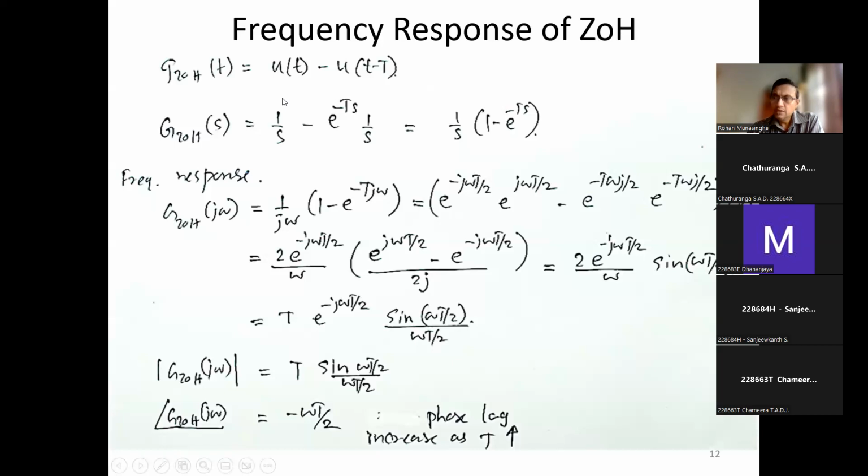So earlier we saw that the transfer function in the continuous time domain, right, is this one for the zero order hold. Have you got that? We gave it an impulse and we got the response. Of course, you know, if you give just an impulse to the zero order hold, you get the step, just one step, one time sample, right?